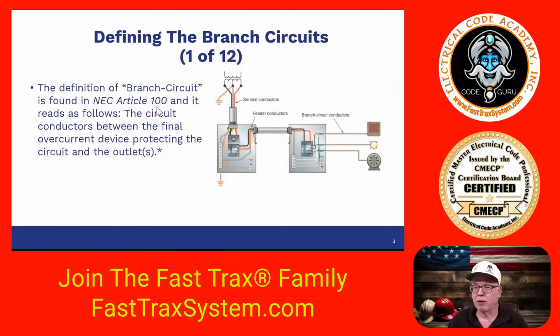All right, so the first thing that we want to talk about is obviously what is a branch circuit? What makes up a branch circuit? Well, as you can see in the illustration here, we have the utility coming in right here. These are the service conductors. They hit this main disconnect, which is the main service disconnect in this case. And then on the load side of that, you have this feeder breaker. This feeder is feeding a remote distribution panel downstream. And in this case, it's a main lug only, as it's within the same building, and it's protected upstream in accordance with 408.36. So all those rules are met.